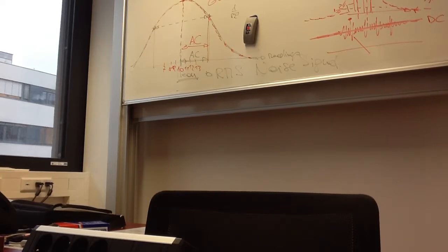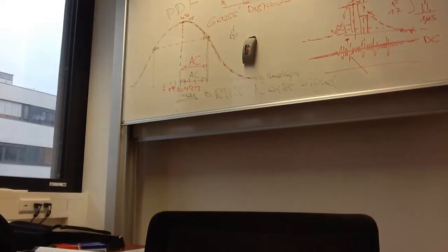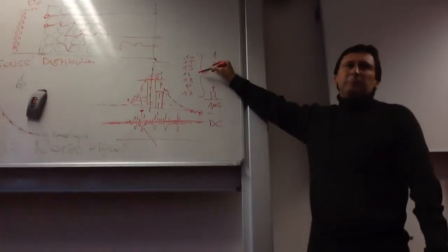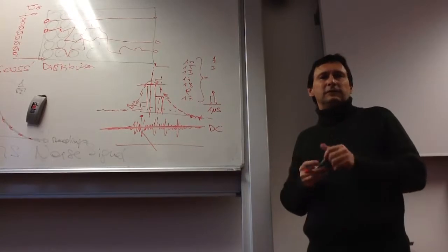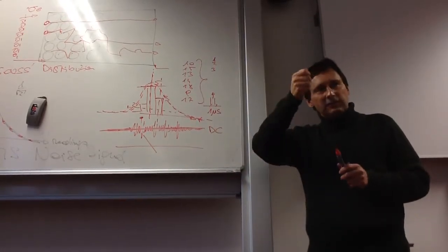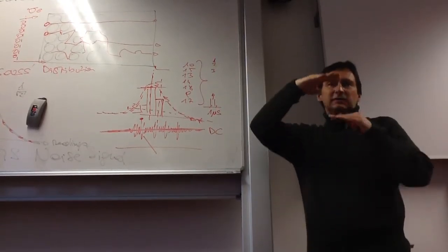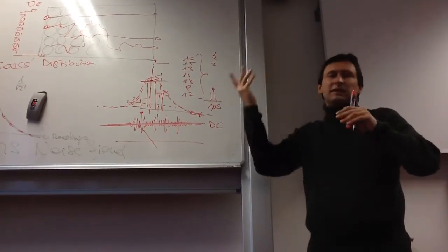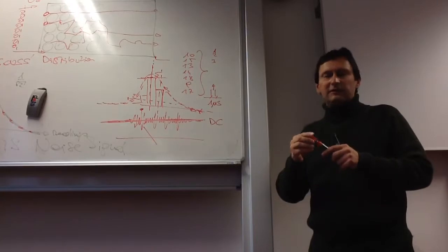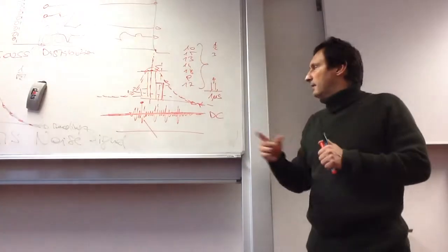Because for the stochastic signal we cannot state an amplitude, because the amplitude is changing all the time. You can try this with your oscilloscope: increase the resolution, and you see that this will go apart, and you cannot see a curve, and you cannot have a measurement value.